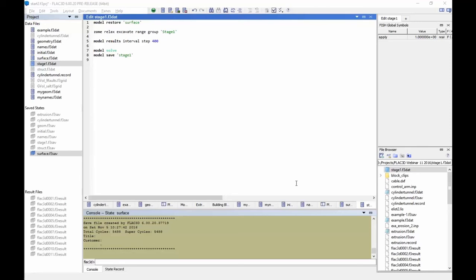You can also specify a local axis system to override the system that's defined by default by the face itself. So, for instance, you want to apply a stress that's not aligned in the direction of the face, you can do that either way. And that also applies, by the way, to velocity-based constraints. Even if the face is at a weird angle, you can fix it at the normal velocity, and it will resolve all those constraints, even in areas where those intersect. So, for instance, doing a pie-shaped model is much easier now than it was before.